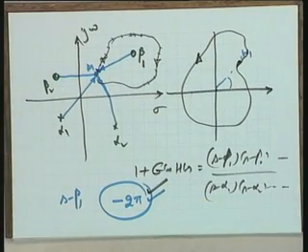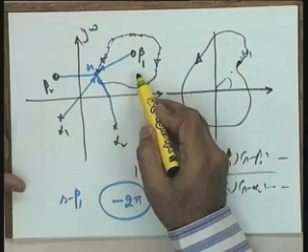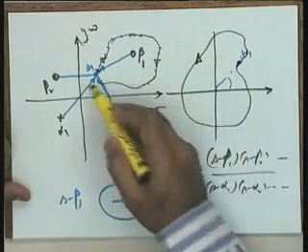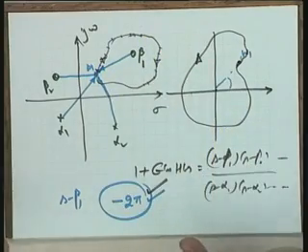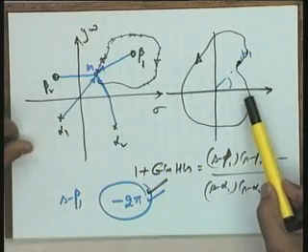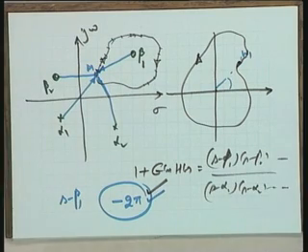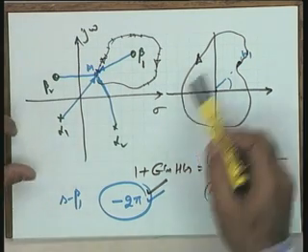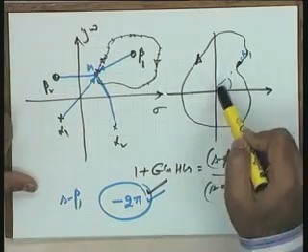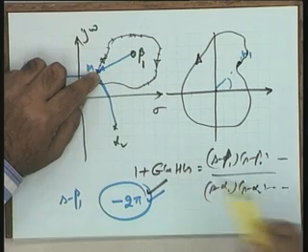See this point, please. On this I am going to base the criterion, and the criterion will become very simple. If there is a 0 enclosed by this S plane contour which you have tentatively taken, then in the corresponding W plane there will be a contour, the shape may be anything. I am not going to do the calculations because I am not interested in the shape, but this is sure: this contour will enclose the origin.